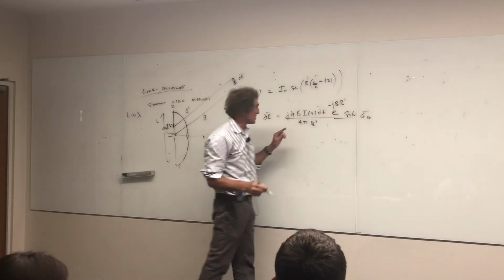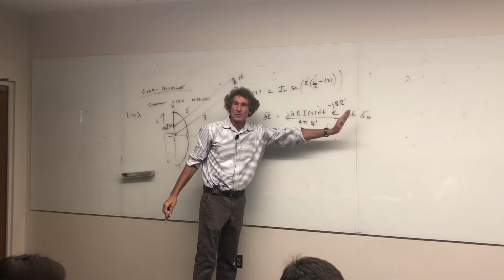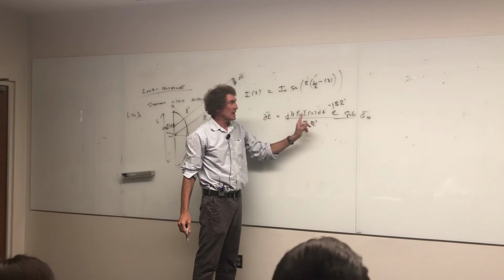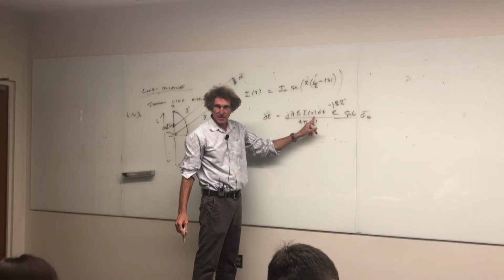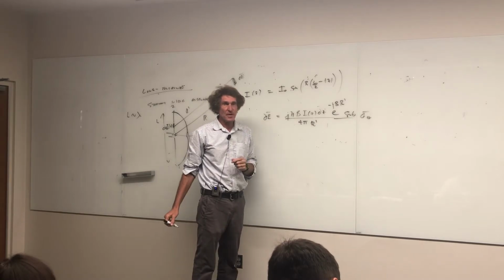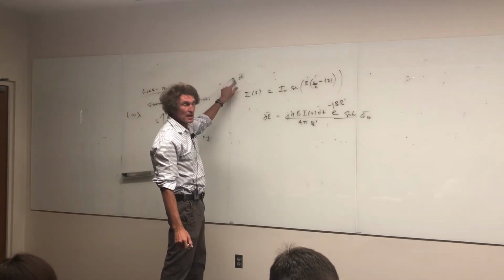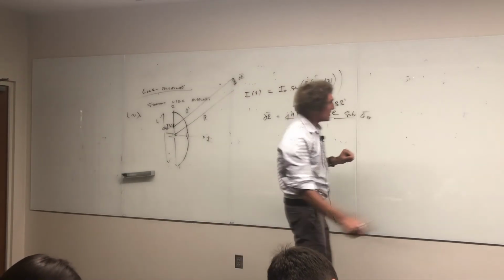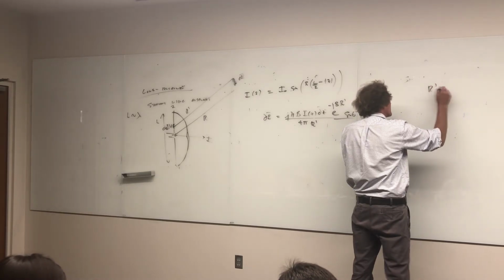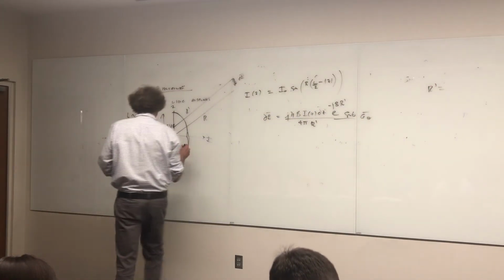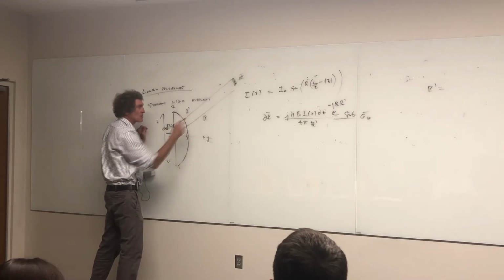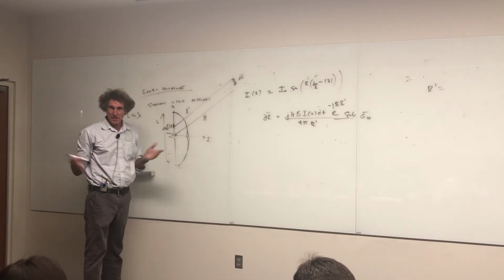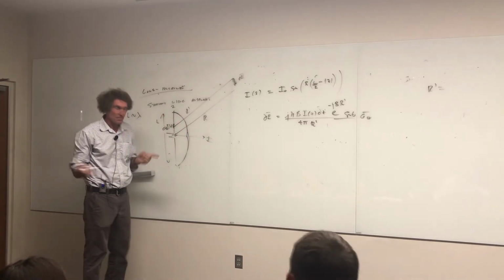Now try to appreciate this. The only thing I've done is take the electric field for a short dipole. I've replaced the dl with dz and the I naught with I of z, because it's a function of the position z. So this is the differential electric field at this point here. Now something to be said is this e to the minus j beta r, because r itself, if you look there, my r prime. Now take a look at this. Try to appreciate what I'm saying. These two are almost the same length. If that's r prime and this is r and we're in the far field, this total distance is much, much greater than the length of the antenna in the far field. Got me on that? Now keep watching.